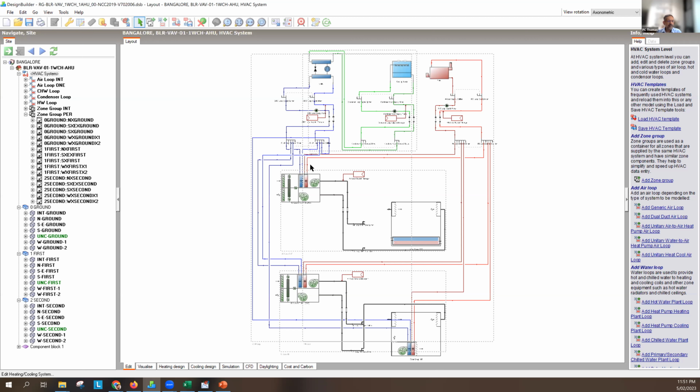In some cases, you are calling it a dedicated outside air system, but that's a very specific term. But you need to think about how you are controlling the air temperature, because now that's independent of the radiant system. Okay. So in some cases, people use what we call neutral air. So you're always sending in air which is about 21, 22 degrees centigrade.